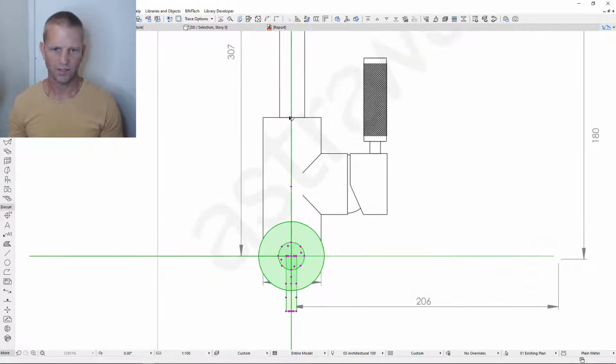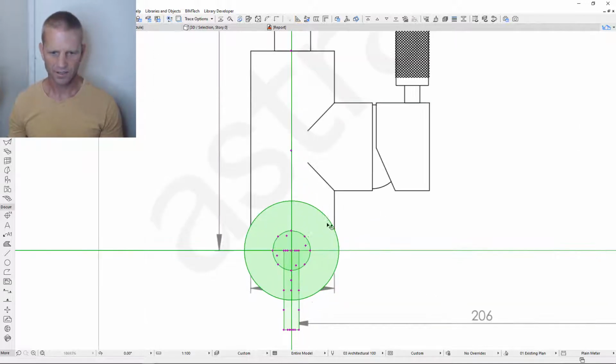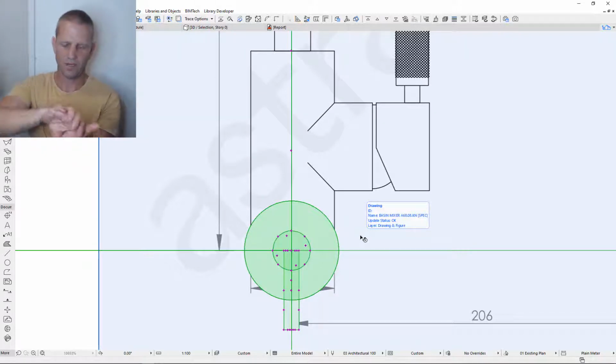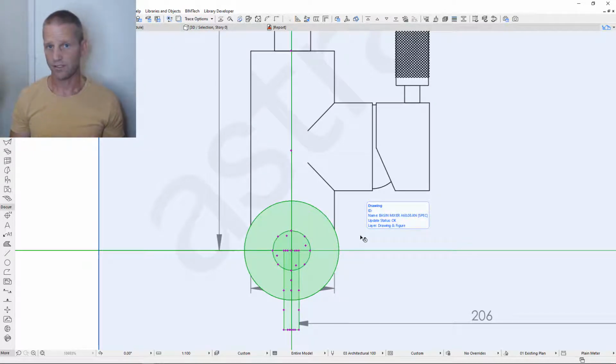The next thing to do is this part of the stem. This is the stem that you can see here, but it's just rotated in order to get it to stand upright, because it's a revolve, and revolves travel along the x-axis. So if you rotate the y-axis, which is minus 90, then it stands that revolve up. So that's how this geometry has been created.